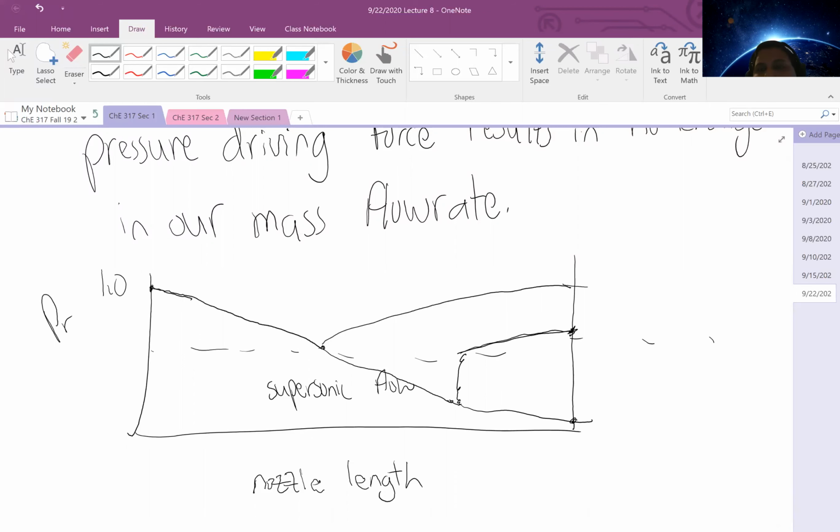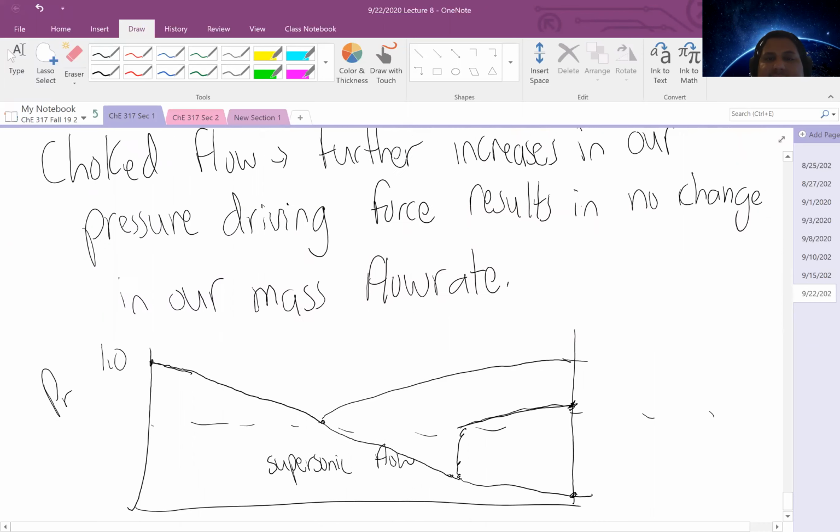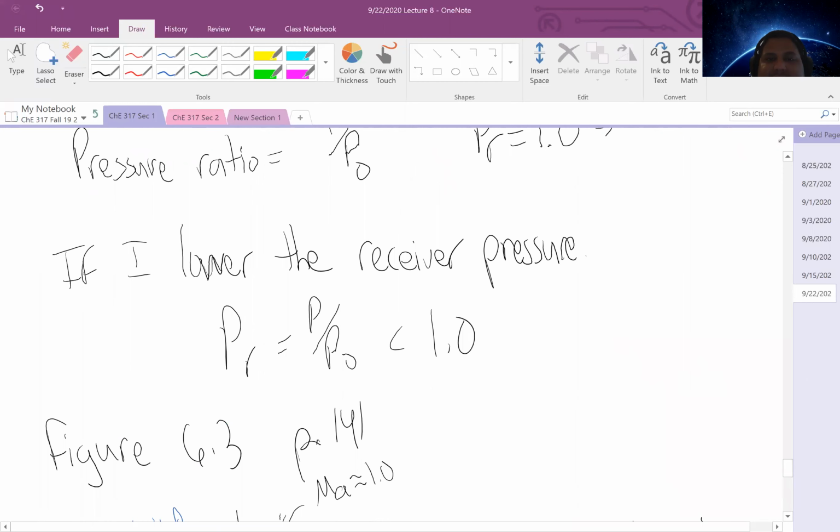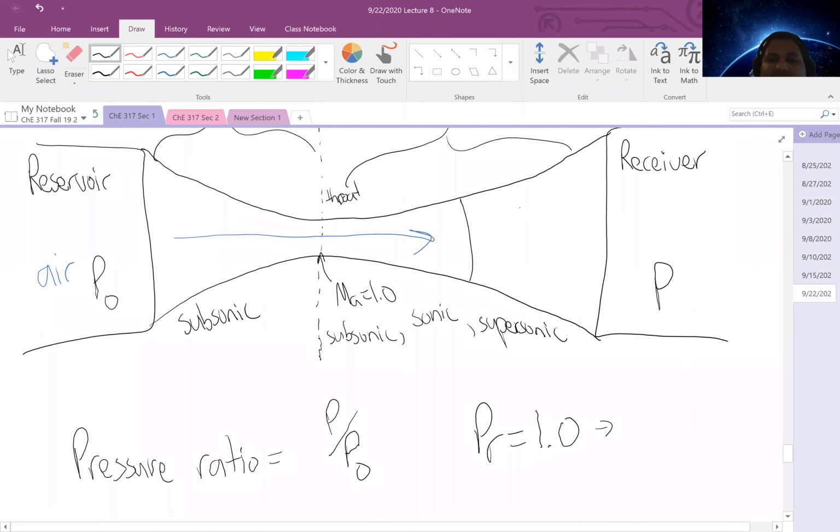It's a direct result of the fact that you're trying to achieve supersonic flow within a confined system. And so that wave propagation has to be set such that it follows the diverging section. If there's any sort of discrepancy, you end up with an actual physical shock that forces your flow back into a subsonic state.